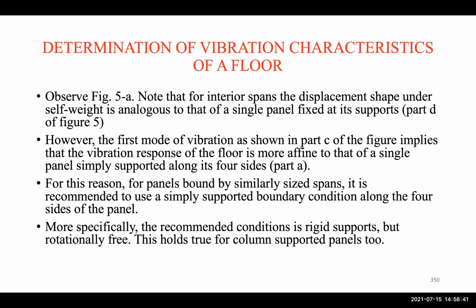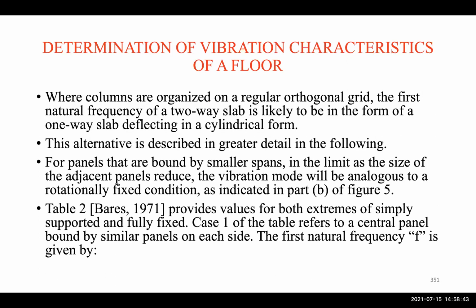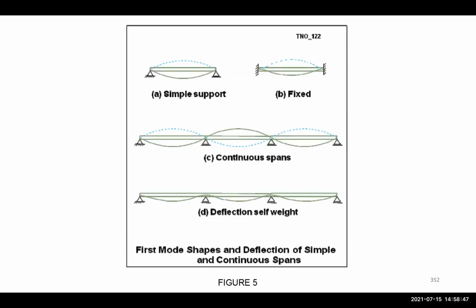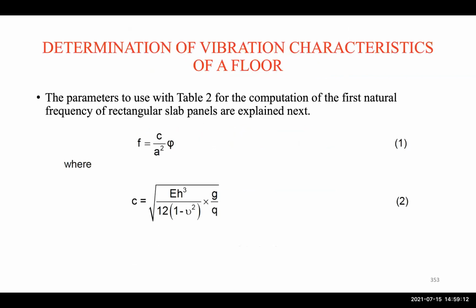So how do we do that? I'll go through the figures. That depends on the boundary conditions, whether we have simple supports or fixed supports. So we have to identify the boundary conditions that we have, and of course whether it's a continuous beam or a simply supported beam. So that makes a difference.